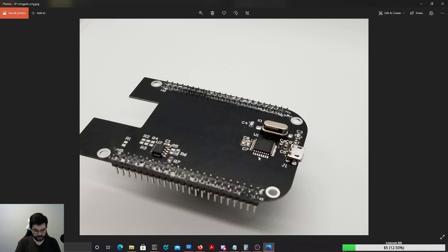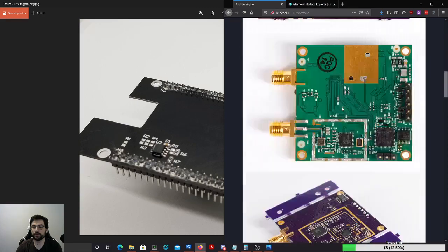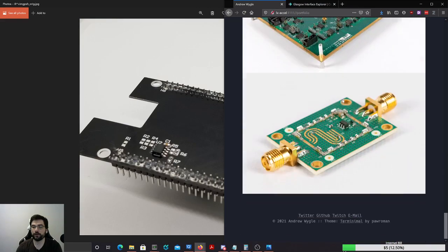It's thin. And I did that so that I could hit the target impedance, and it did work, but the problem is that the board will just flex, right? Like I can just bend it in half, and it's a terrible structural problem, especially with all of these connectors. The force to separate them is already really high, and when the board feels like you're going to snap it in half because it's so thin, it's a bad design. What you do instead, by the way, is you do coplanar waveguide, which I was talking about before in the context of this LNA. So this is the same thing except you do a coplanar waveguide.